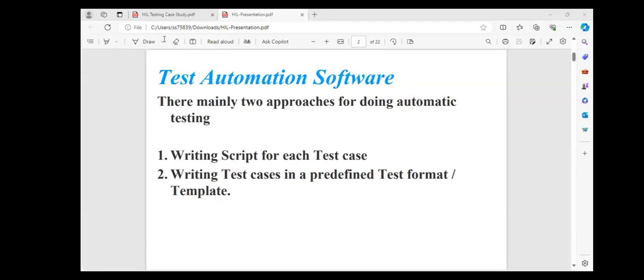Okay, so there is a body control module or ADAS, anything, right? There will be features like adaptive lighting, the 360 view feature, and the lane departure feature. These are the functionalities. In black box system testing, we give the input and we get the output. We check whether the output is as expected by comparing with the actual output.